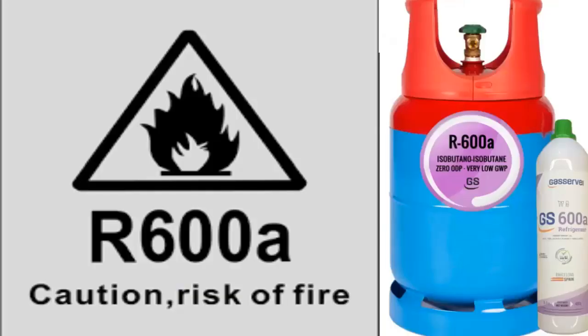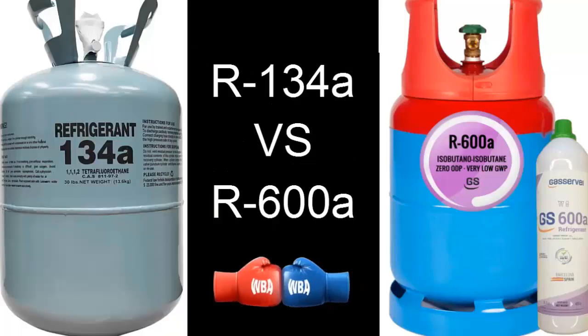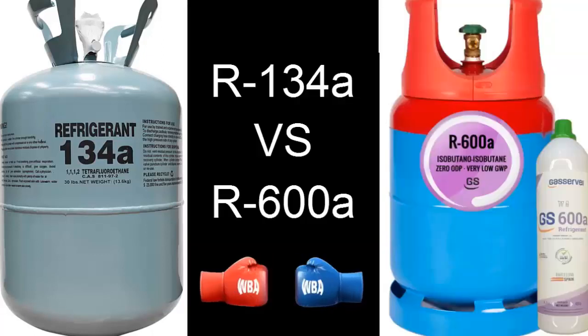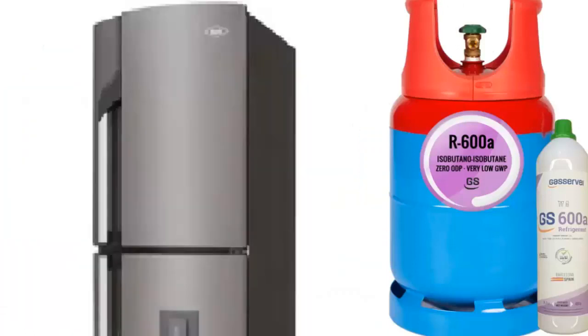R600a, isobutane, has a safety classification of A3, non-toxic but flammable. R134a is non-toxic and non-flammable. Although R600a, isobutane, is flammable, its use in refrigeration systems with lower cooling capacity reduces the risk due to the significantly low amount of R600a refrigerant used.